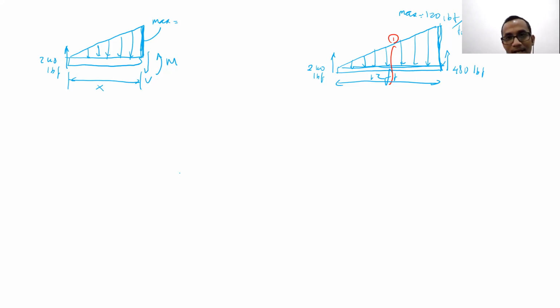But you cannot find the value of the maximum distributed force, right? Okay, so if the maximum here is 150 for the 12 feet, what is the value of the distributed load at 6 feet, exactly in the middle? 60, right? Just now you answered 60 pound per foot.